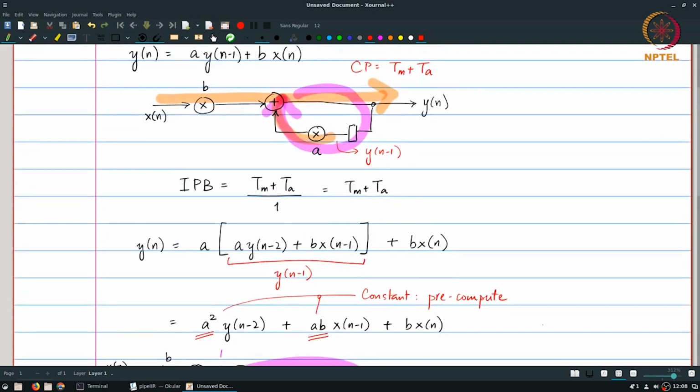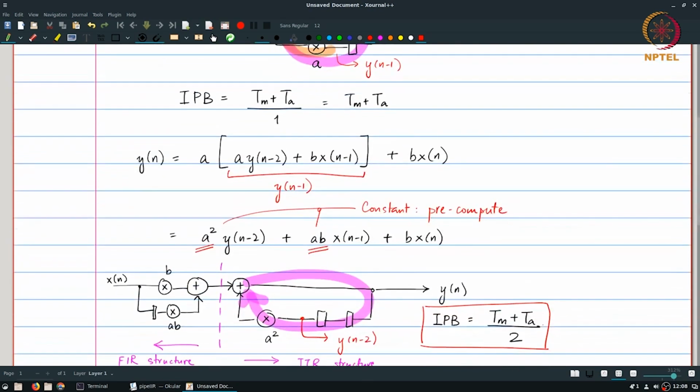The original filter that we started with and the new modified filter that we have come up with are in principle different filter structures. In fact, one of the places where this can actually hurt is the fact that when you start using finite precision and fixed point number representation, you will actually find that even the values that are being computed can end up being different in the two cases.